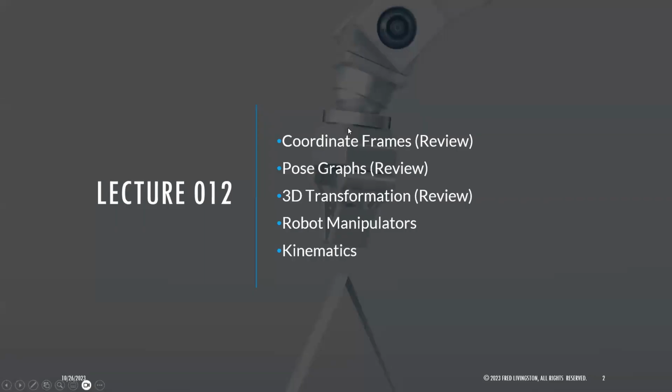Right, so we're going to review coordinate frames. Everything in a robotic application is going to have some kind of frame assignment, and usually in manufacturing as well. If you go to any CNC machine, there's a home position and some kind of coordinate system for that particular scene. If it's 2D, the XY grid. If it's a 3D printer, you have XYZ, and you need to know where that home is. You also need to know where your current tool is in the process, or where it's extruding material, or where the end mill is, depending on the manufacturing process. There's a tool frame, and there's a base frame, and there are coordinate frames for anything in the object there.